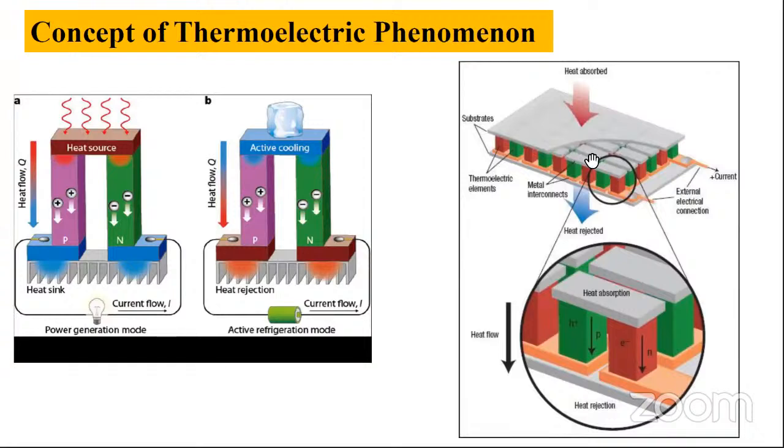In this right hand figure, this is a thermoelectric module. The thermoelectric module is based on all these phenomena. It contains a number of semiconductor pellets, meaning thermocouples, which have been doped and contain one type of charge carriers, meaning P type or N type. These semiconductor pellets are connected in series, you can see in this figure. These are connected in series electrically and parallel thermally.